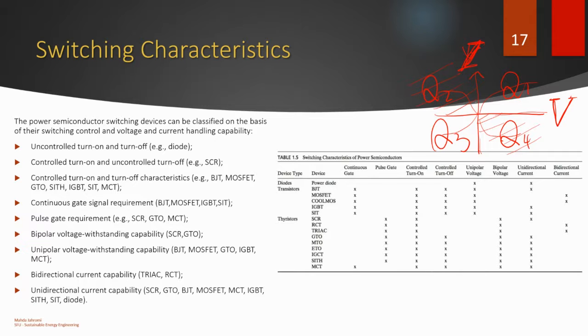So none of these switches will work if you assume this polarity convention, where the current is entering the positive side like a load. If you ever enter quadrant 2 or 4, that means now you have a source. And none of these are sources. These are all passive devices. But some of these may be able to go into the 3rd quadrant. So Q1 and Q3 are for loads, Q2 and Q4 are for sources.